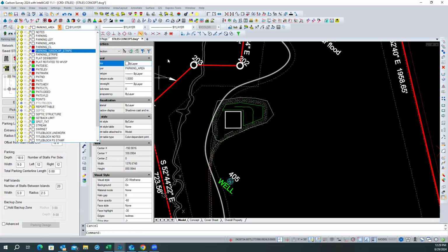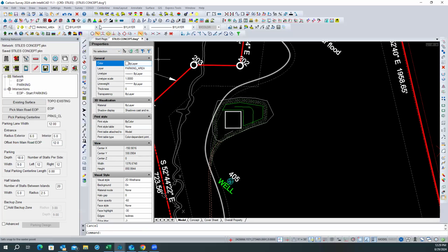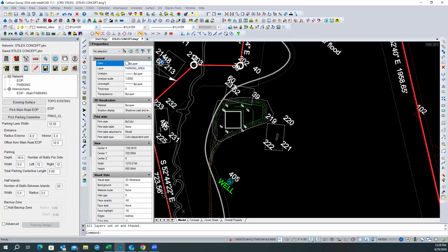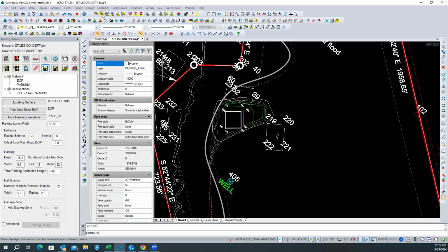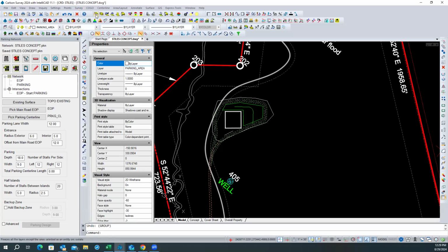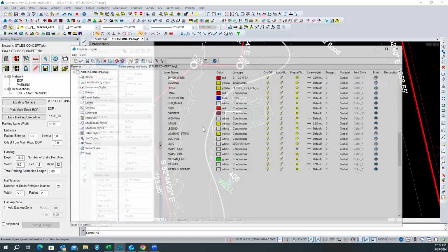Oh, you think they've already been in the drawing? Yeah, I'm pretty sure that they have. All right, let's turn everything on. There they are. Let's find out what layer it was. Points frozen. Okay, so we'll go back to where we were, and we're just going to thaw. Points frozen for the moment.